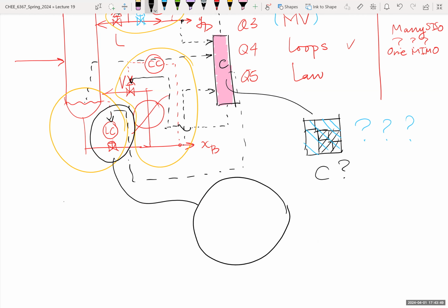Namely, you may have here the control valve. You measure the flow rate. You have a flow controller. And the measurement that comes from above is essentially the set point to this controller. So this is called cascade control. We'll spend a little bit more time on it, but it's a standard control scheme that is used extensively.